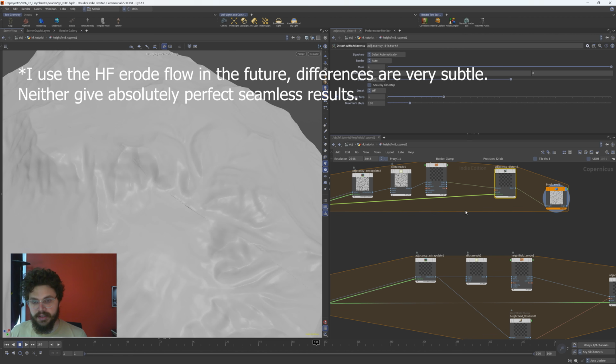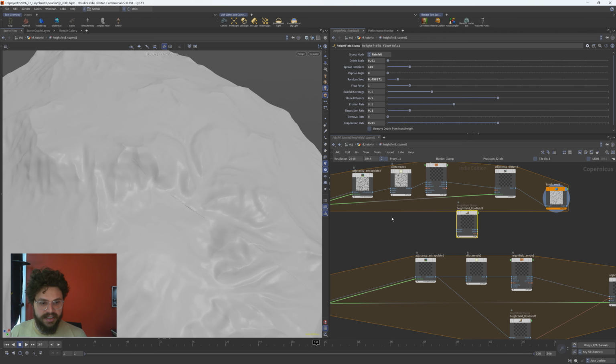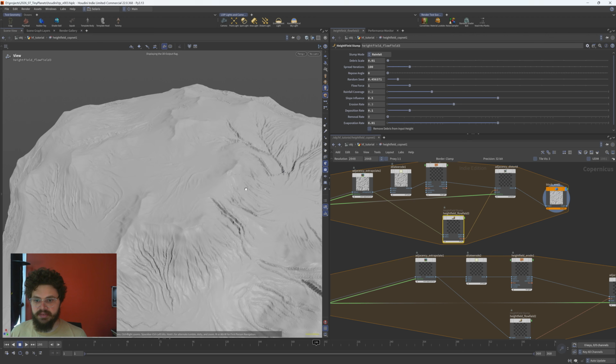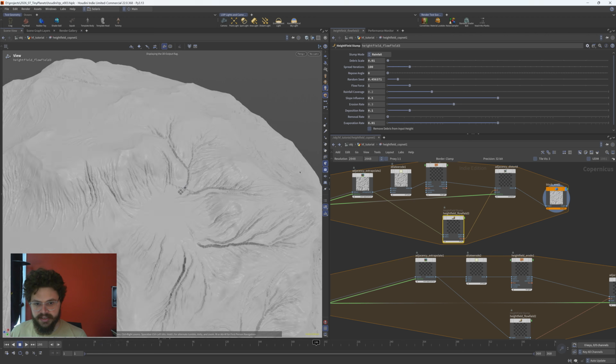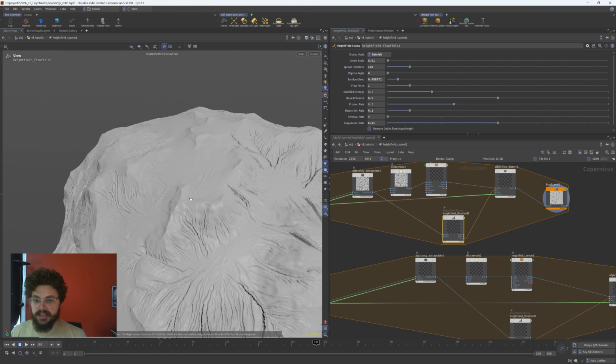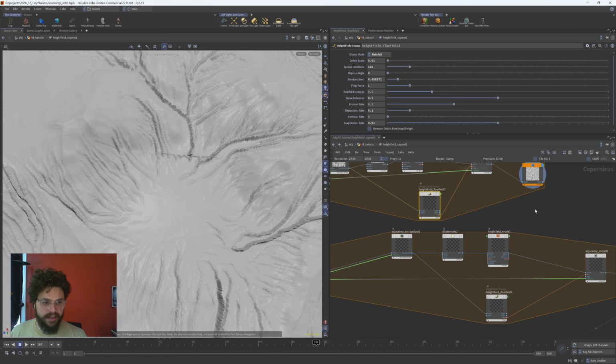This is all sort of theoretical. I use the Heightfield flow node and just hook that into my original extrapolate and use that flow parameter to drive the direction. And you can see once I do that, this is pretty powerful, but it's starting to cover up some of those seams. We can still see a little bit here, but if we sort of glance around, we really aren't noticing much seams. This is probably the most egregious point right there.